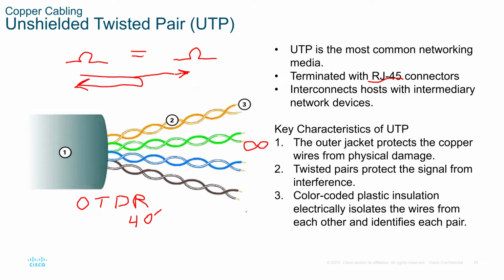In a corporate environment, the documentation should tell you how long a particular cable is. If you put the TDR on the cable and it tells you that it is not as long as in the documentation, you now know that you have a break in that particular cable and approximately how far from where you are the break actually is.